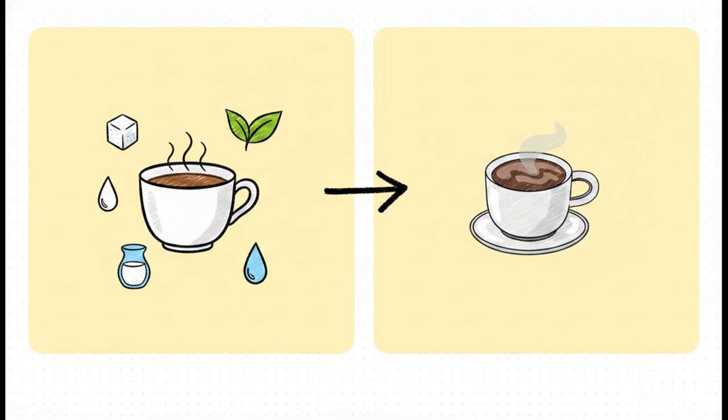Or think of it like a tea shop. You're the owner, and you prepare one perfect cup of tea. Now you tell your employee to make exactly the same tea. If the sugar, the milk, the tea powder, and the water are all absolutely identical, the taste of that output perfectly matches your reference. The current mirror works exactly like this. A reference transistor prepares the current, and the output transistor copies it. But it relies entirely on having completely identical ingredients.